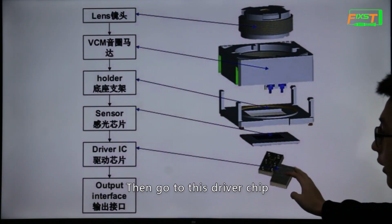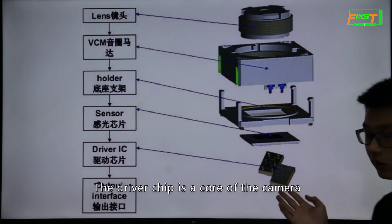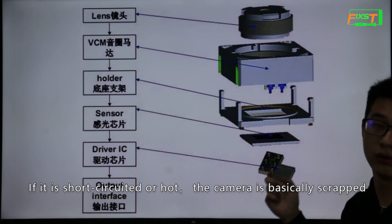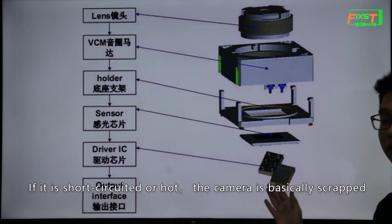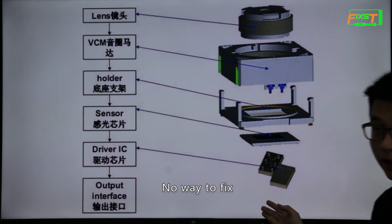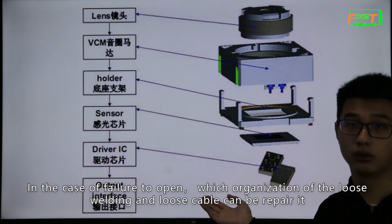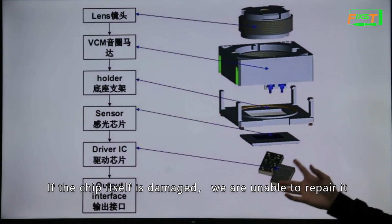Then go to this driver chip. The driver chip is a core of the camera. If it is short circuited or hot, the camera is basically scrapped. There is no way to fix it. In the case of failure to open, problems like loose welding and loose cable can be repaired. If the chip itself is damaged, we are unable to repair it.